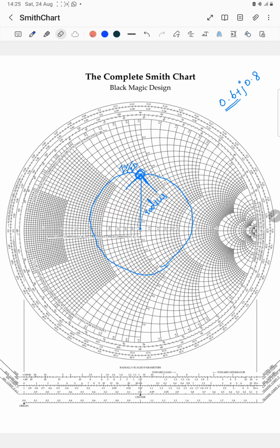So after drawing that circle, you should extend this line. Wherever it cuts, extend this line. If you draw it with a compass, it exactly cuts this point, that is 3. We should mark this; it is nothing but the VSWR. You should directly calculate it from this. On the right side, on the line x equal to 0, where the impedance circle intersects, this point is the VSWR.